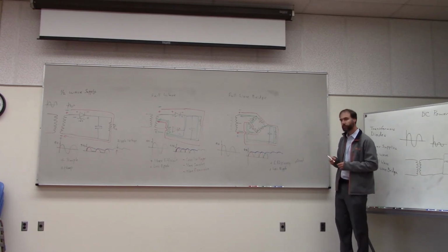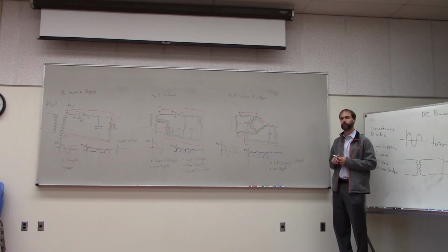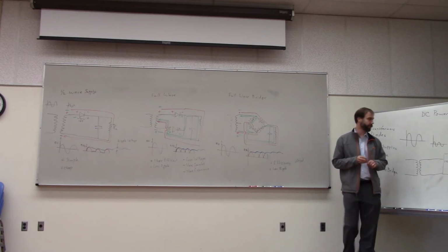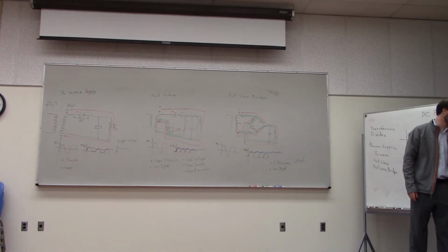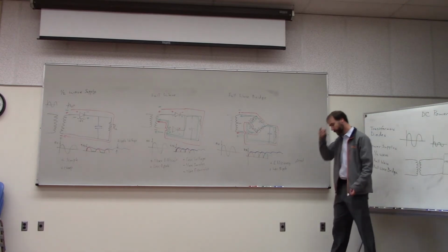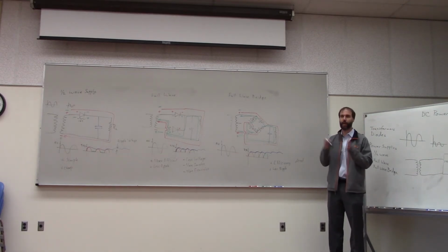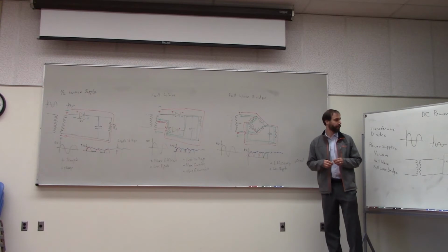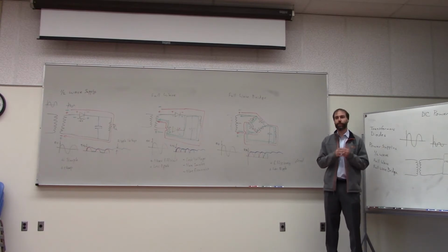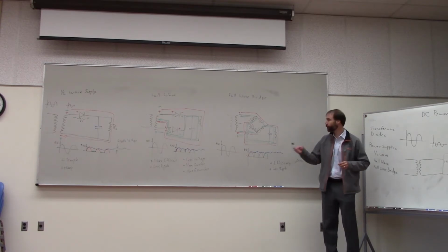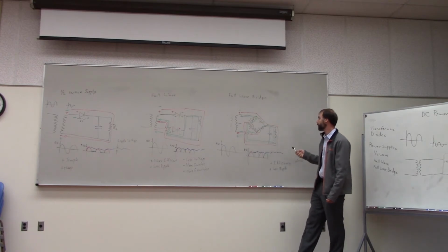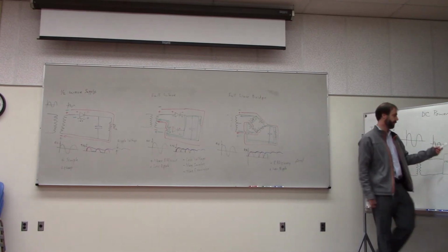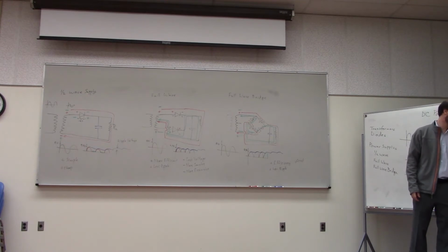So, yeah. What's the difference between one of these and a switch mode power supply? So the switch mode power supply uses a switch mode regulator, and that's actually what I was alluding to a minute ago when I was talking about the high frequency thing that chops up the signal. Basically, a switch mode power supply is what most types of electronics use these days. And the first part is really a full-wave bridge rectifier. The thing that makes it the switch mode power supply is the type of regulator that it uses.